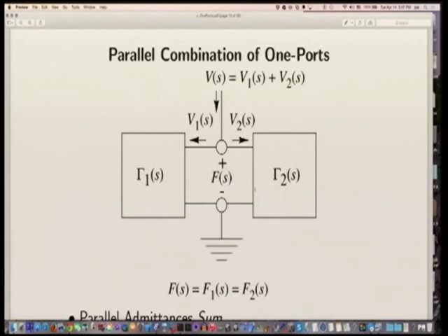That's what it's called lumped circuit modeling, where you have R's, L's, and C's. The frequencies in the circuit are low enough that you don't have to think about transmission line effects in the wires connecting the elements. So if an element goes up and down in voltage and there's a wire that connects it to another element, it is assumed that that element will go exactly up and down in phase. In other words, wires carry one voltage, and they instantly transmit that voltage from element to element. And that's what you call the lumped case.